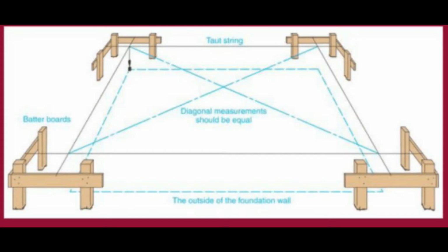When you are putting up profile boards or what is seen as batter boards, there's always an allowance measurement that you have to add to the board to allow persons to work in the area when they are doing preliminary work without affecting the profile or the batter board. So in this case, we are going to be adding an additional 4 feet. Either way, essentially we are adding 8 feet to the length and 8 feet to the width, and then we are going to times it by 2.